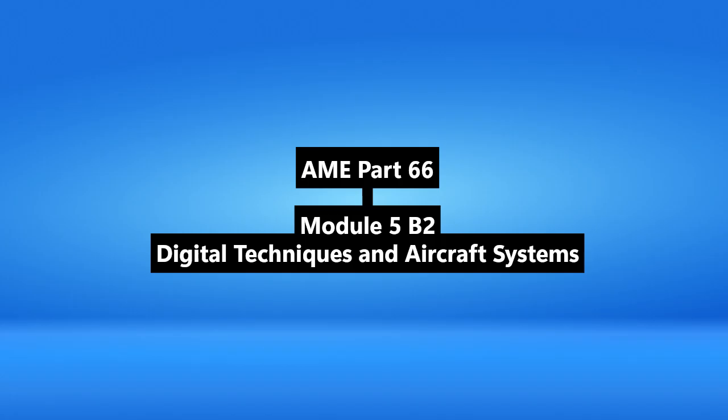Active matrix LCDs, or AMLCDs, especially those using thin film transistors, TFTs, are much better. Each pixel gets its own little transistor switch right there on the glass. This allows much faster, more precise control of each pixel individually. Result: faster refresh rates, much better response time, critical for showing rapidly changing flight data, sharper contrast, wider viewing angles. AMLCD with TFT is the standard for modern electronic flight instrument systems. Right, that clarity and speed is essential.